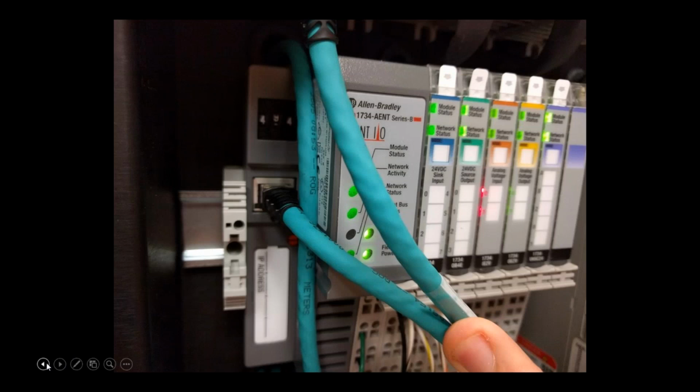we're going to talk about the Ethernet I/O, or the Point I/O. Something that's important to note is when you get an Ethernet I/O out of the box, what's on this thumb wheel right here is extremely important. It usually comes out of the box saying 888, that means that it has been set up to get an IP address through BootP.